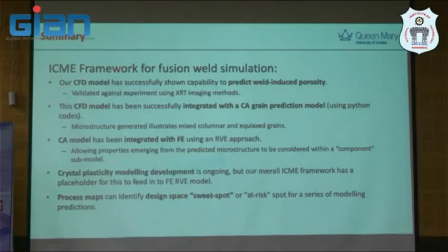And this is integrated into the cellular automata grain prediction model. We do a lot of data processing to generate the microstructure, to represent the real microstructure from simulation. And this has been integrated into the finite element calculation using a representative volume element approach. And this one can predict the component in the submodel analysis.